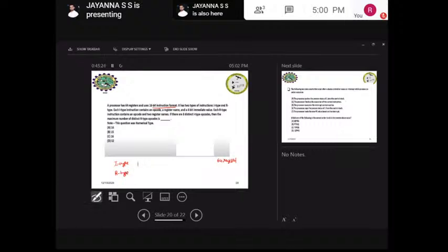If you consider I type, it contains opcode, register, then a 4-bit immediate value. If you consider R type instruction format, it contains opcode and then 2 registers, R1 and R2. And the total length is 16 bits because it uses a 16-bit instruction format.